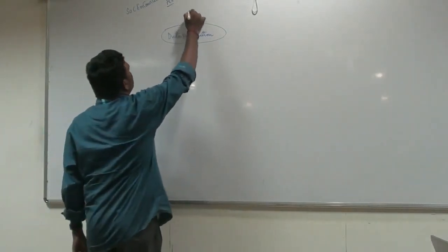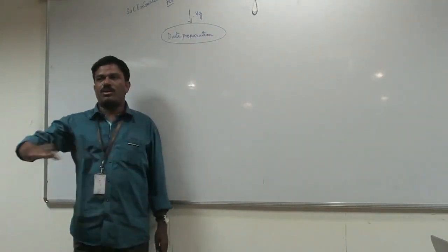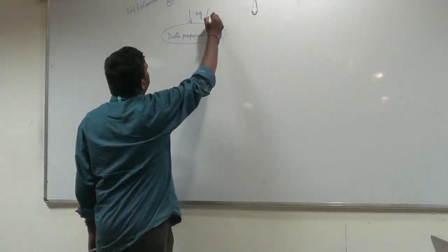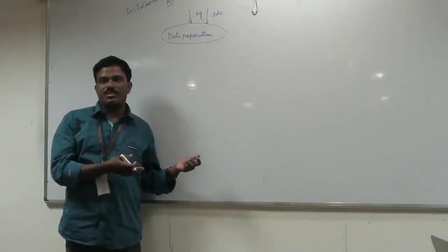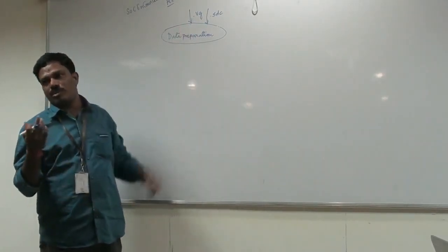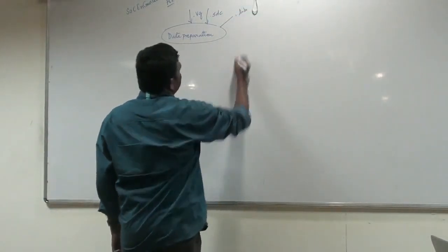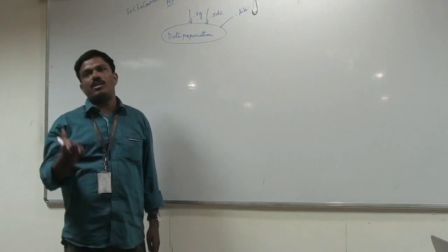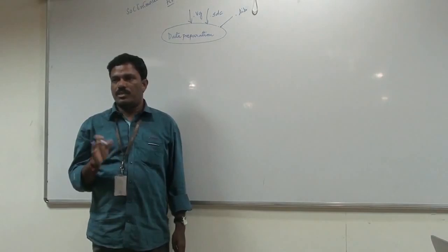Okay. So what data we need to have before going for the backend? First input is the gate level Verilog netlist, generated from either Design Compiler or RTL Compiler, whatever tool you use. Okay. Then in the same way please obtain the Synopsys Design Constraints .SDC. That is also generated by the synthesis tool. You have to specify the constraints, and based on the constraints, the tool will give you the SDC. Okay. Apart from that, we need to have the lib, that is, library files for a particular node. So if you are working for 45, we need to have the 45 lib. If you are working for 20, we need to have the 20 nanometer library.